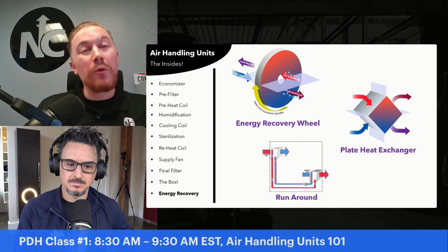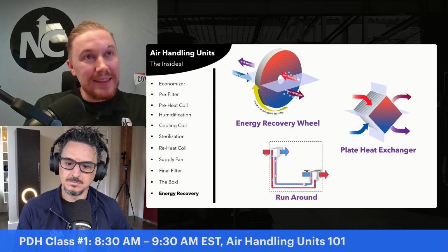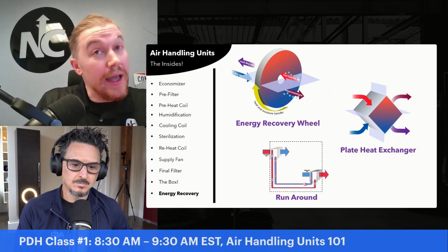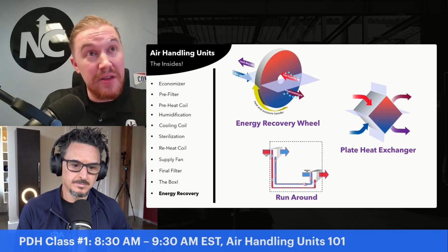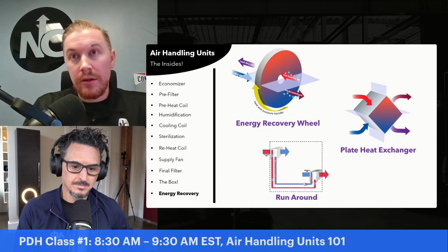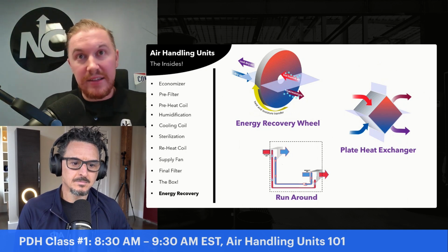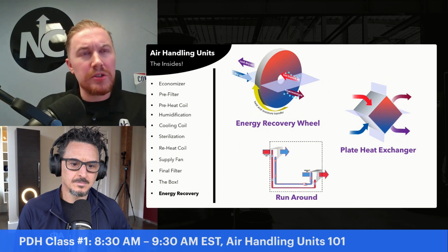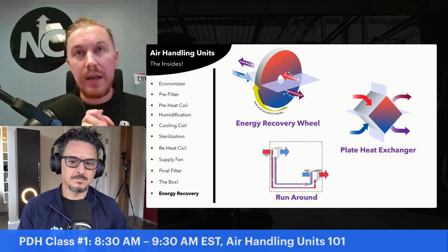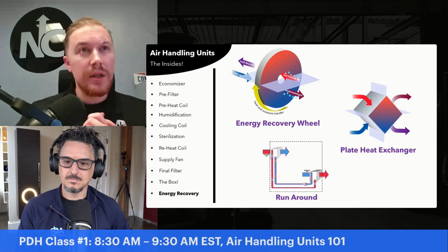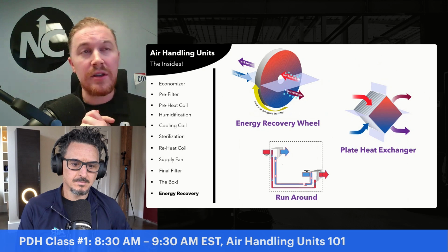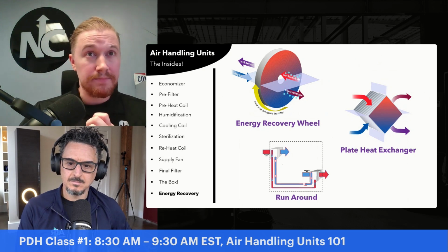Okay. So for sensible and latent energy recovery, we can use energy recovery wheels, and we can use plate heat exchangers. We have enthalpic plate heat exchangers that will do both ends of the energy, both latent and sensible. Most of the time, most people probably see plate heat exchangers as a sensible only type of energy recovery. The important notes about these recovery options are contamination.